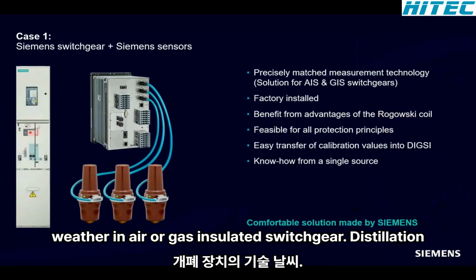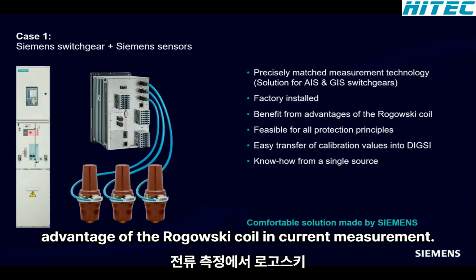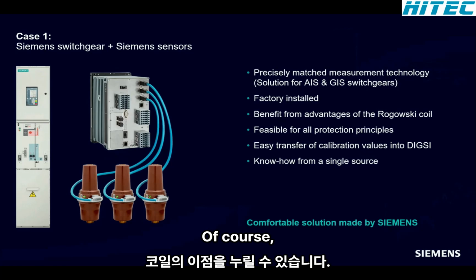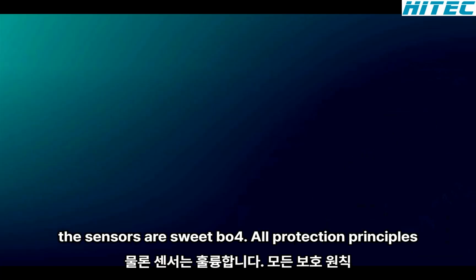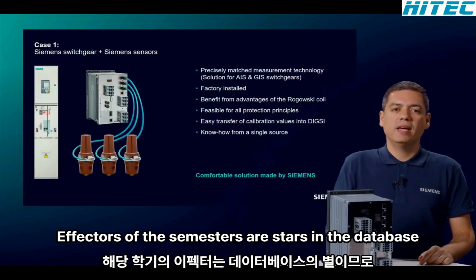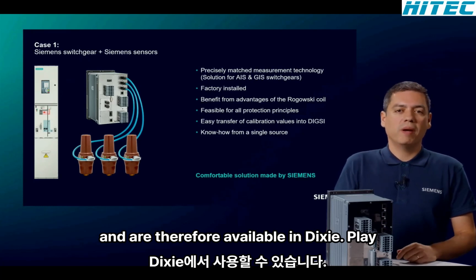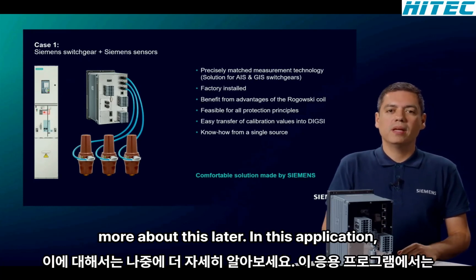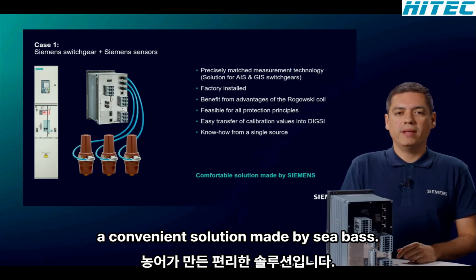The installation takes place in our switchgear plants, and you benefit from the advantages of the Rogowski coil in current measurement. Of course, the sensors are suitable for all protection principles. The correction factors of the CME sensors are stored in the database and are therefore available in DIGSI. Lars will explain more about this later. In this application, you will receive the know-how from a single source, a convenient solution made by Siemens.